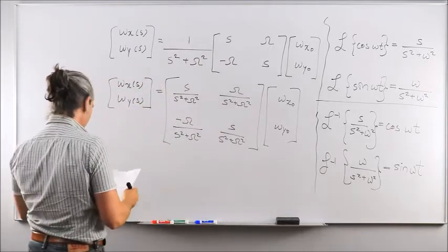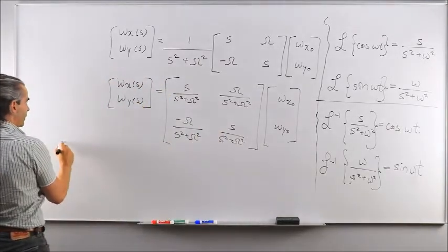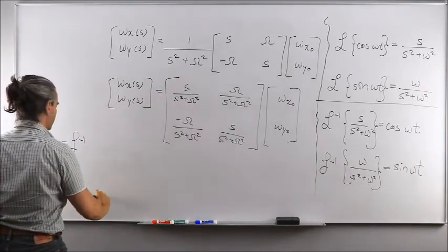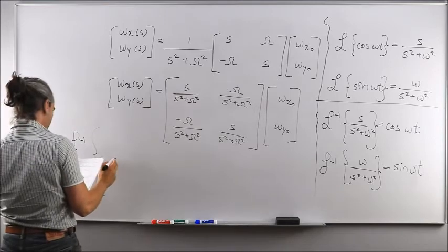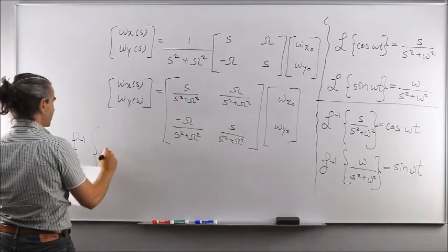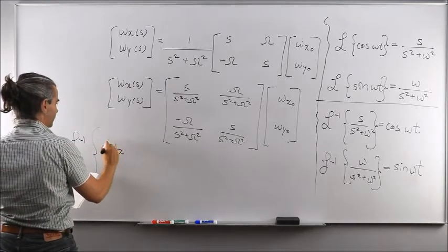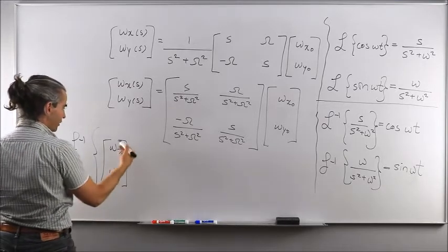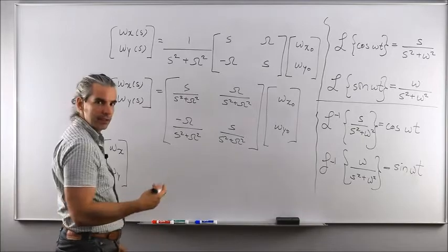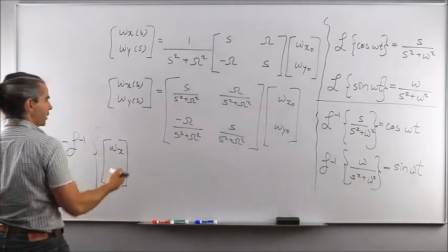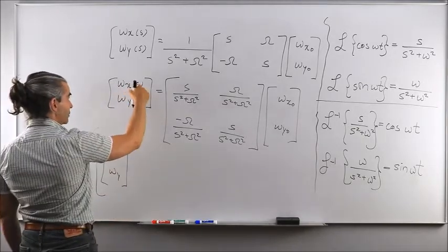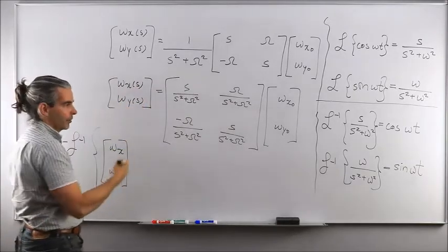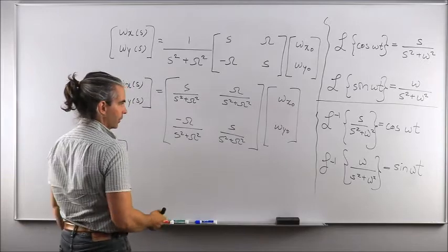So there, I am then applying the Laplace transform over this matrix equation, which would then give me omega x, omega y as function of time, and I am omitting the time dependency for conciseness, okay? Whenever we're in the S domain, I was explicitly writing function of S, but I'm not going to do that for function of time because otherwise I'll keep writing forever, okay?